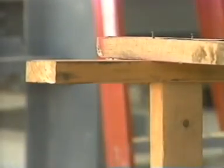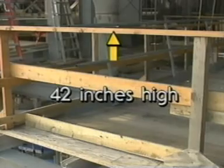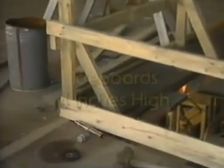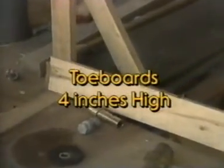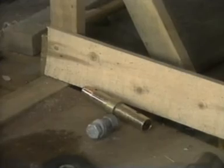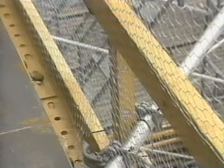The top guardrail should be constructed of 2x4 lumber, or the equivalent, and positioned at a height of approximately 42 inches above the platform. Toe boards at least 4 inches high should be placed close to but not resting on the scaffold platform. To prevent the dislodging of materials stacked higher than the toe boards, a screen or wood paneling should be used to cover the area between the toe board and the guardrail.